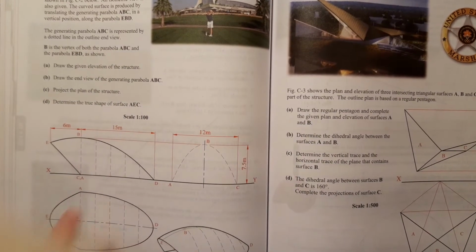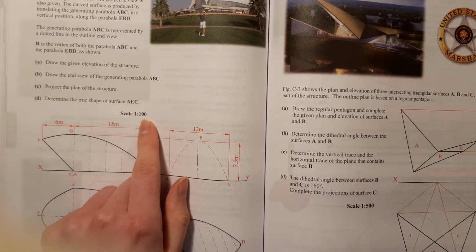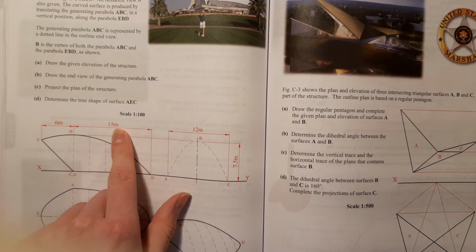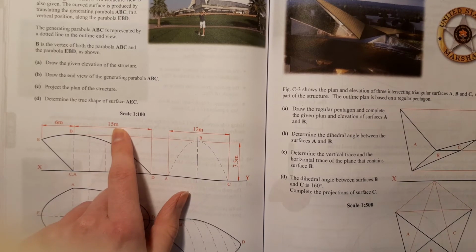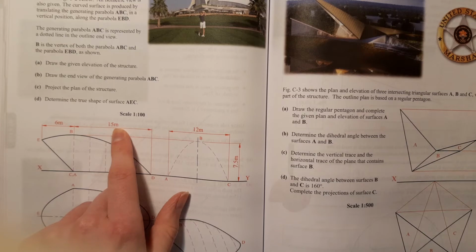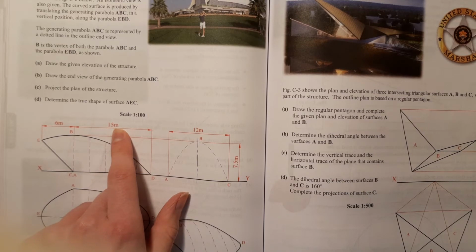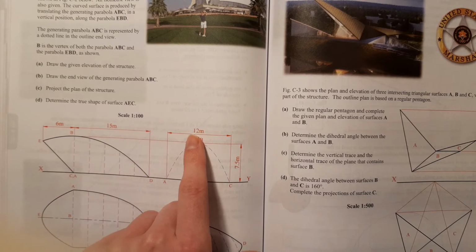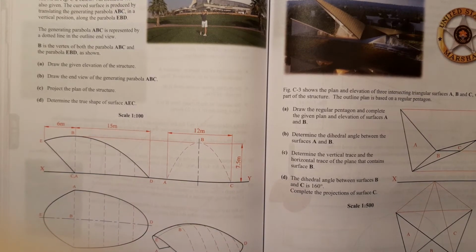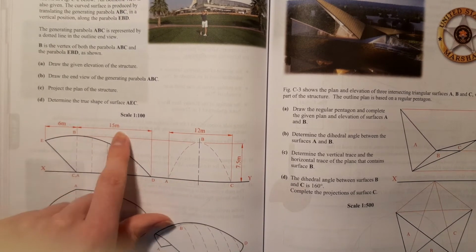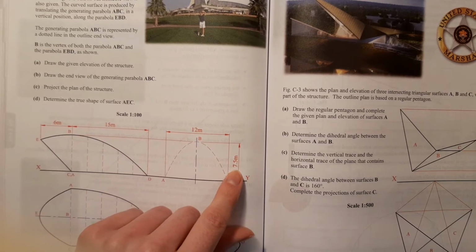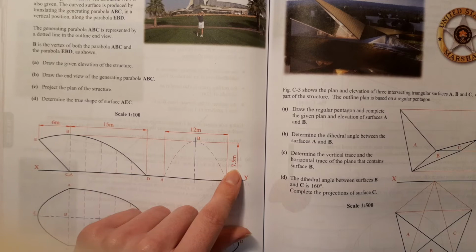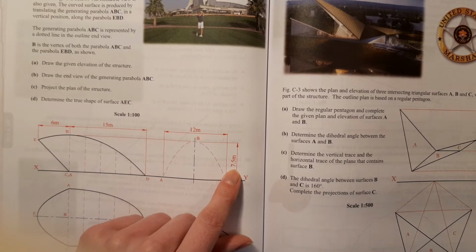So just to explain it, at scale 1:100, that means with every measurement that's in meters, you change it to millimeters first. So that's 15,000 millimeters divided by 100, that would become 150. So basically with every measurement, you're putting on a 0 to each one. So 6 will become 60, 15 will become 150, 12 will become 120, and the height, instead of it being 7.5, will be 75. You're multiplying by a unit of 10.